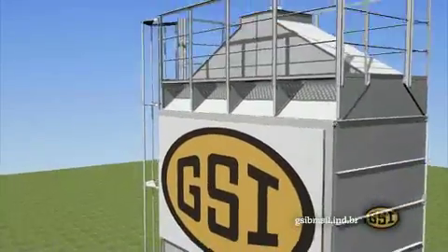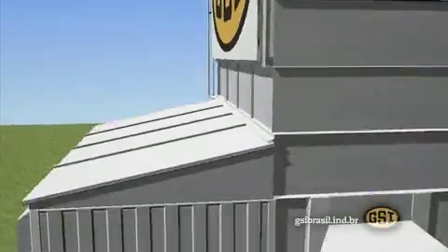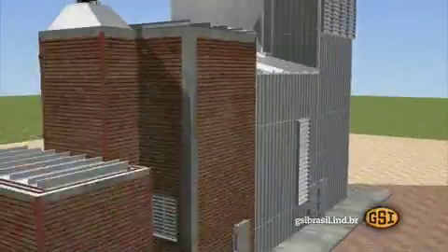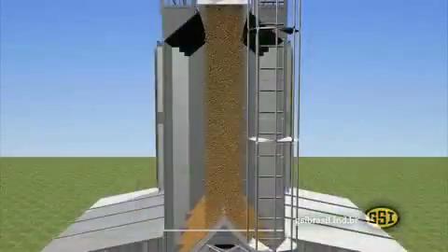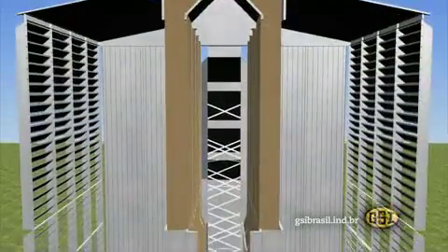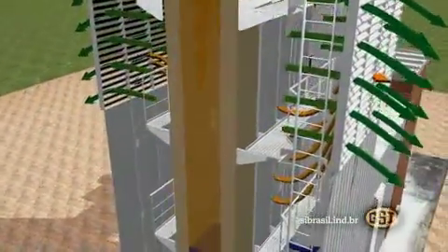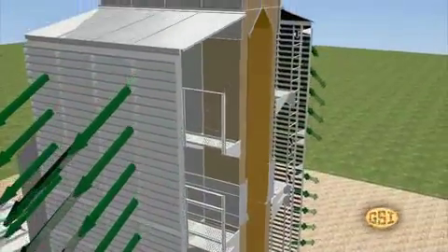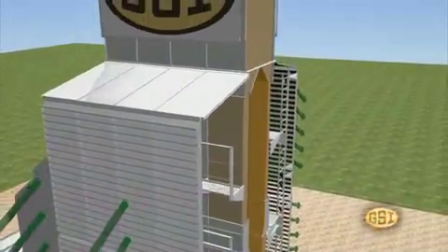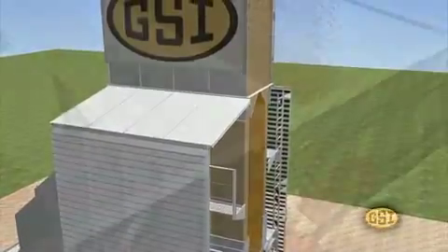The process dryer dries much faster. Whereas in a conventional dryer, the grain remains in contact with the hot air for around 5 hours, as with corn, for example, the process dryer reduces this time to approximately 1 hour and 15 minutes, using cleaner and less aggressive hot air. Grain leaves the dryer with almost no smoke odor.